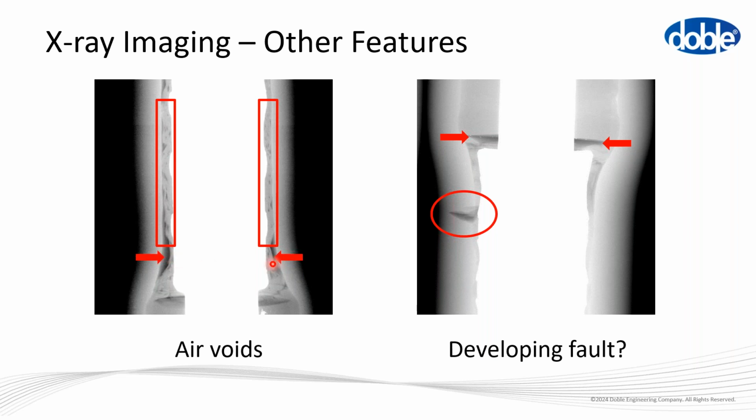So we have some air gaps here. And these are layers of tape over the conductor connector, and we'll see that in an image in a minute. But I can even see that there are air gaps in those layers of tape, between those layers, which are probably only 100, 150 microns thick each tape.